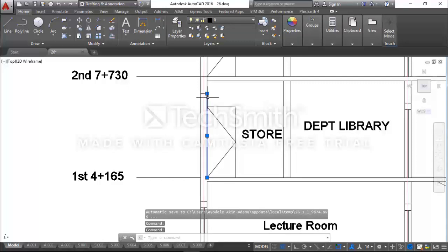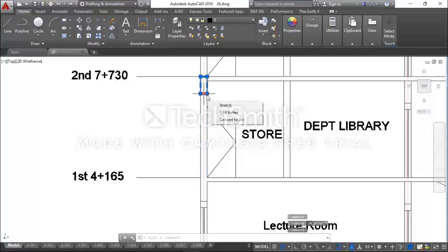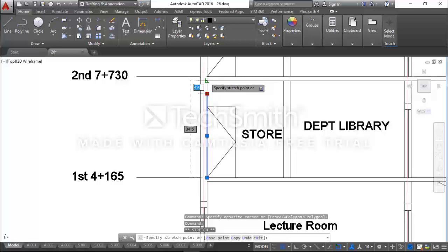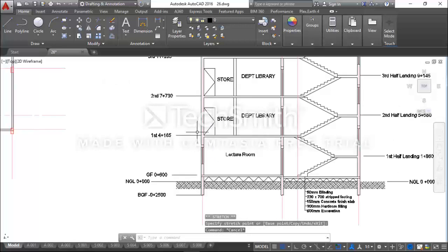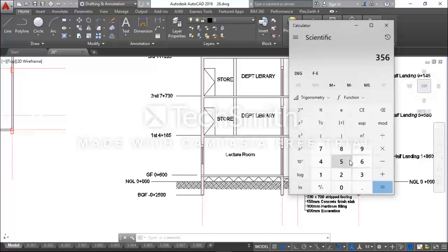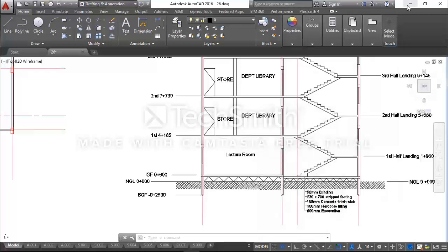I just want to explain this to you, so you understand how you will not use the full height of your structure as the height of your wall. If I'm to calculate this, normally I know my floor to floor height is 3565 and my beam is 600. So I can say 3565 minus 600. This is 2965. So my height of the wall is 2965 for region with beam elements. So 2965 is what I'll use as my height of the wall. Please note this dimension. I'll minimize this and also minimize this.